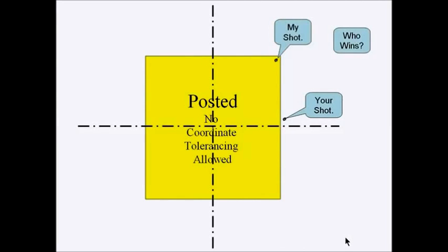When the posted sign appears, explain that if they're using plus-minus tolerances, your shot would be good where theirs would be bad. For instance, if they were using plus or minus 5 thousandths on a drawing, this shot is further away than 5 thousandths. And even though your shot could be as much as 7 thousandths away, it would fall inside the plus minus 5 thousandths tolerance zone.